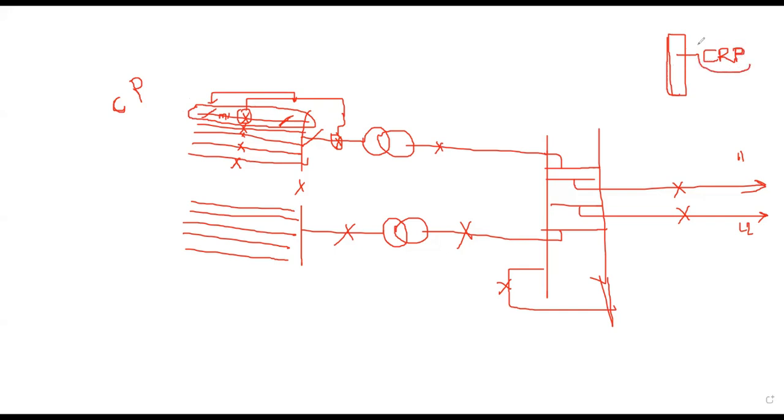So the control and relay panel accommodates all the CT circuits, CT signals, and the breaker status, breaker open and closing circuits, breaker tripping circuits, isolator indication, control and indications, AC circuits, DC circuits, the AC routing and the DC routing, and other such things. So today we are discussing this control and relay panel, how the scheme looks, and how to review the scheme.